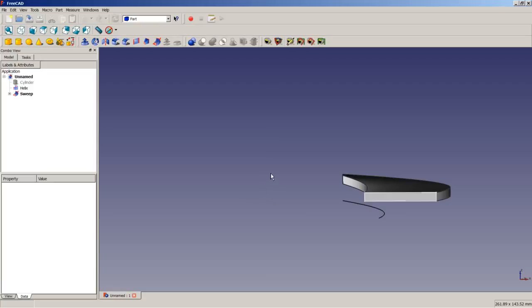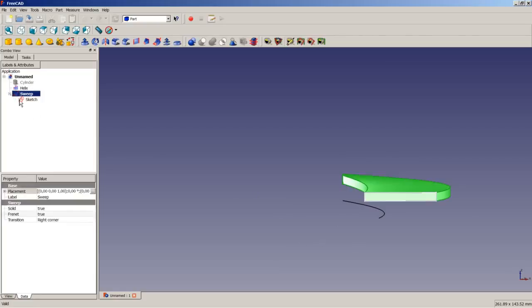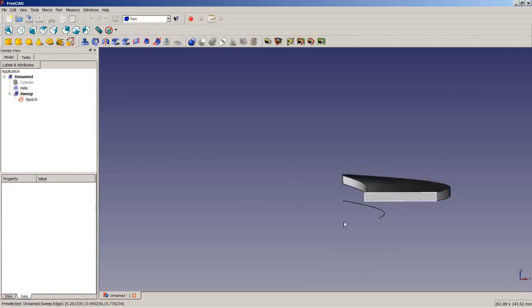In the Part Design workbench, if we do a sketch and apply a pad or pocket operation, the sketch is turned invisible after the operation is completed. And here, the sketch and the helix are still toggled visible after the operation is finished. This is a difference in the workflow of these two workbenches.